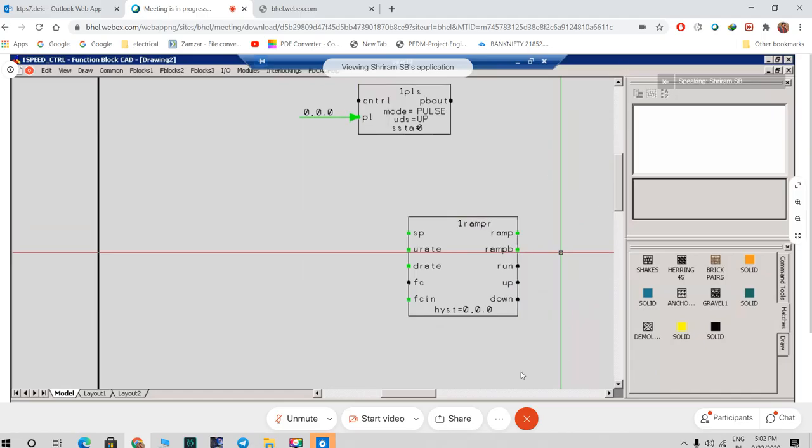What the increase or decrease is, is based upon your maximum and minimum limits. Whenever X is positive, it will go towards the maximum limit, that is, ramping will be in the upward direction. And whenever X is negative, ramping will be towards the minimum limit, that is, in the negative direction. That is the main function of this INT block, and it also has a tracking function with this S and I. Whenever S is 1, the integrator block will not bother about X and T. It will directly give the input I to the output whenever the S attribute is 1.